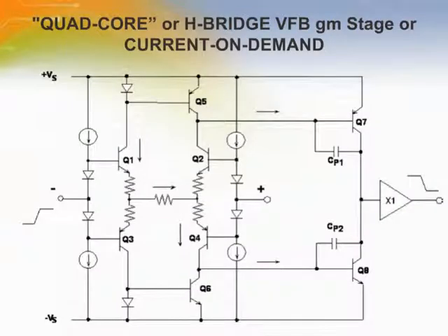Until recently, op-amp designers had to make the above trade-offs between the input GM stage quiescent current, the slew rate, and distortion performance. ADI has patented a circuit core which supplies current on demand to charge and discharge the dominant pole capacitor CP while allowing the quiescent current to be small. The added current is proportional to the fast slewing input signal and adds to the quiescent current.